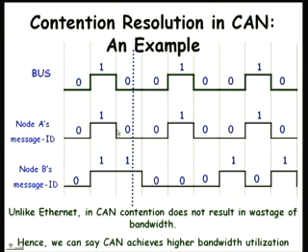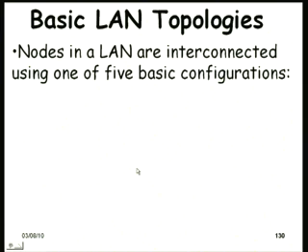Okay. So, what it means is that a lower priority number, priority 1, is a higher priority than priority 10 or priority 20. But if it was the other way around, that priority 20 is a higher priority than priority 2 or something, then when a 1 is transmitted, it will transmit 1 on the bus, right. And once it hears that what it transmitted is different from what is actually shown on the bus, then it will just drop out, it will not transmit. So, I think some other part of the example I forgot to give there, but that is the basic idea.